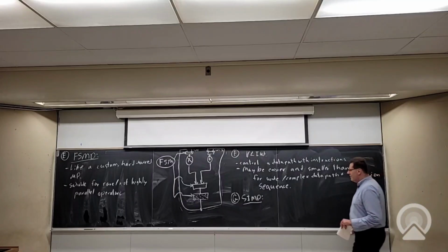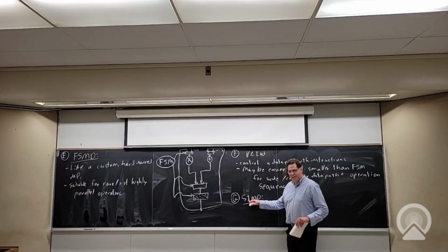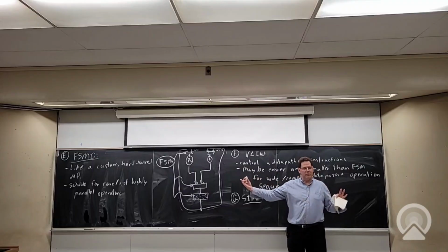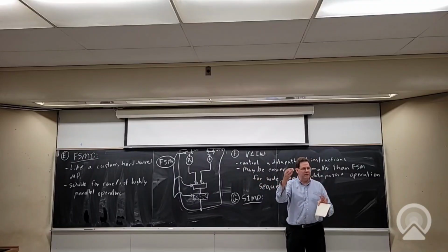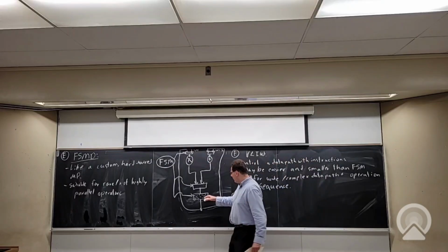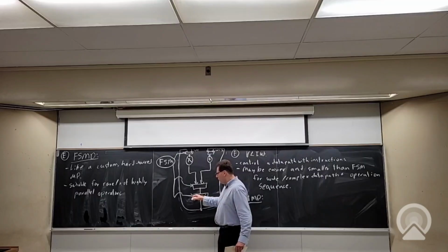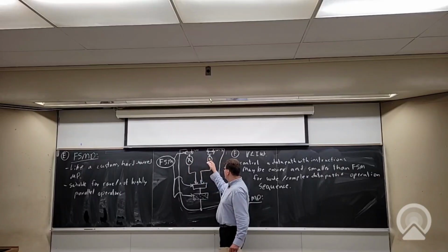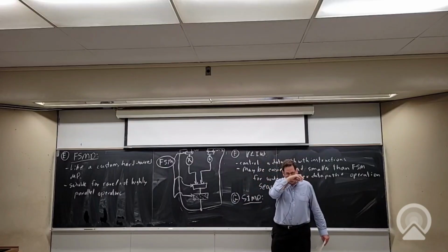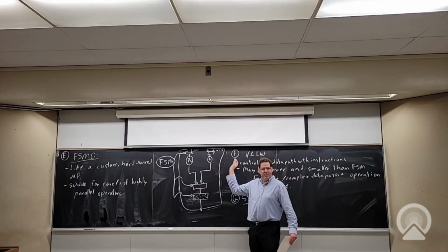Yeah, so I'll just repeat that so people hear it. So a single instruction, and it controls, whereas VLIW basically is a long instruction, every piece of it could be controlling a different functional unit, so something totally different. So one piece of my instruction word for VLIW might control which register I'm reading from, which register I'm writing to, what the multiplier is doing, what the adder is doing, what this mux is doing, and maybe some more stuff, right? Because usually for VLIW, I'd have some more operators up here.